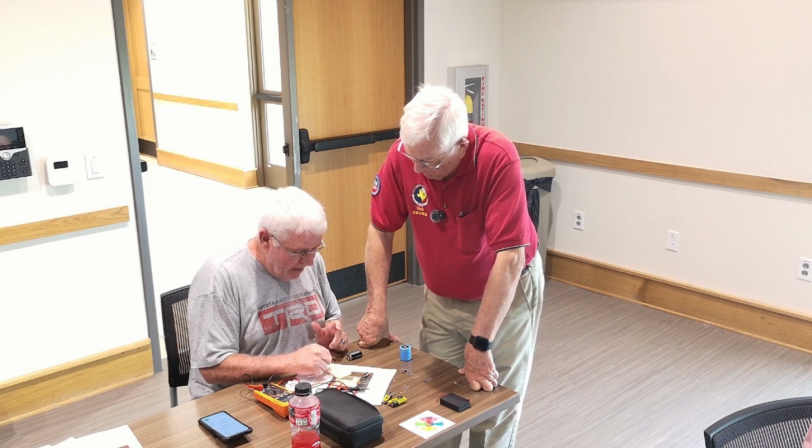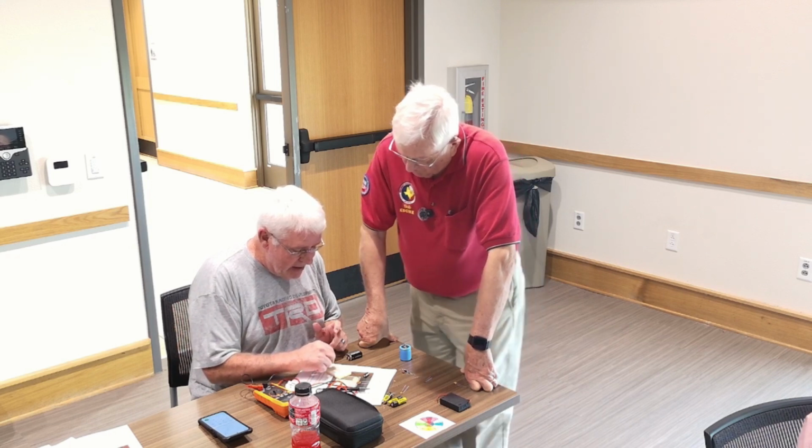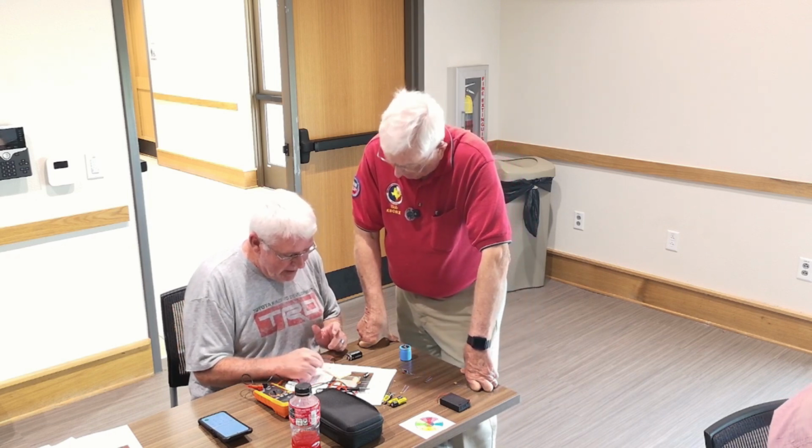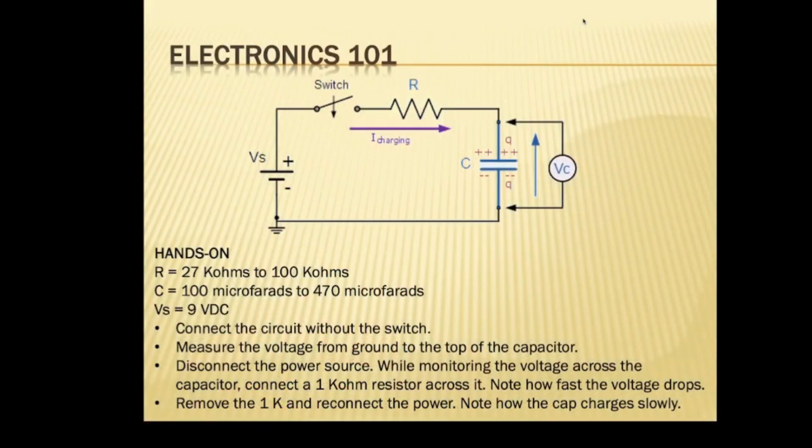Then we put the capacitor in a row, and we can put the resistor in the same row, connected to the positive. That keeps the circuit going all the way through. And if we want to hook something else to this same row, we could plug in a jumper there and take it to wherever it needs to go, because we can do a jumper from one row to another.